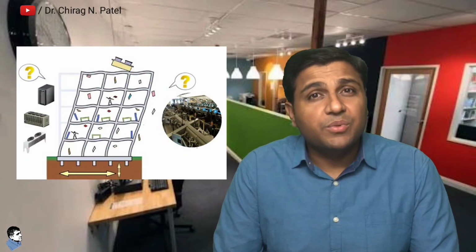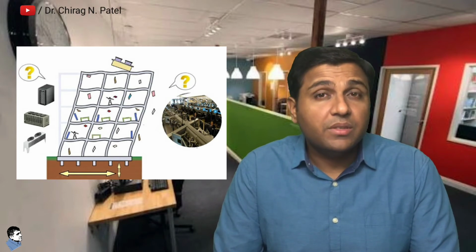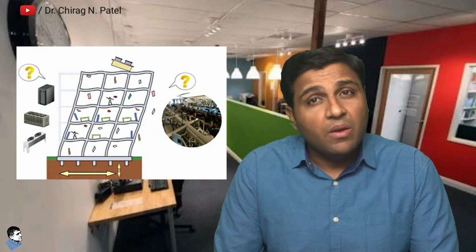This is because non-structural elements such as claddings, partitions, and pipework must be able to accept the deflection imposed on them during an earthquake without any type of failure. Failure of external cladding, blockage of escape routes by fallen partitions, and ruptured firewater pipework all have serious safety implications. However,